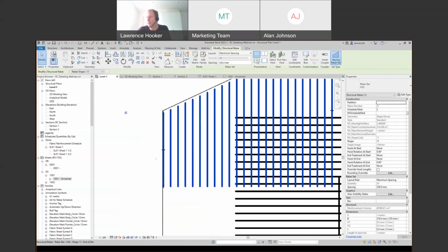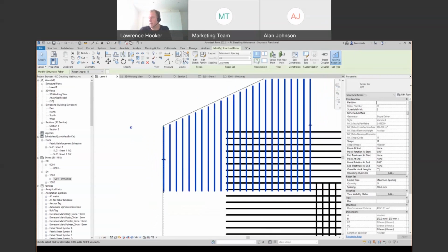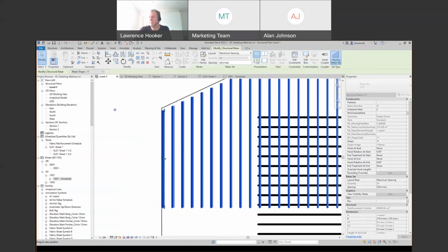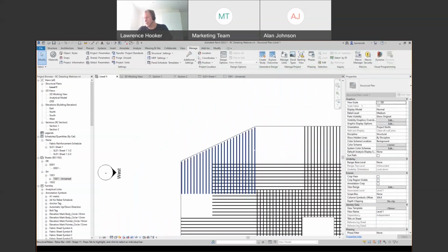Okay, so it's simply just that nice little shape handle down here that can control whether it becomes a skewed range like that or a varying range. Okay, so I'm just going to go for varying range in there. Obviously we can adjust the start and the end point of that range. Of course, we can use rebar constraints again to ensure that that is exactly where we want it.